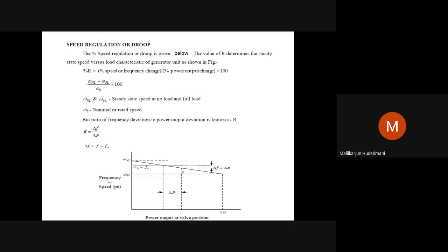Steady state operation of the governor means what? The governor has set a point and kept quiet, and the machine is operating. On notice of a drop of frequency, the governor will again act, correct it, and keep quiet for the next observation. Like that, governor based operation, which is by droop, a fall in frequency or RPM for a subsequent change in load, will correct your operating point to the requirement.